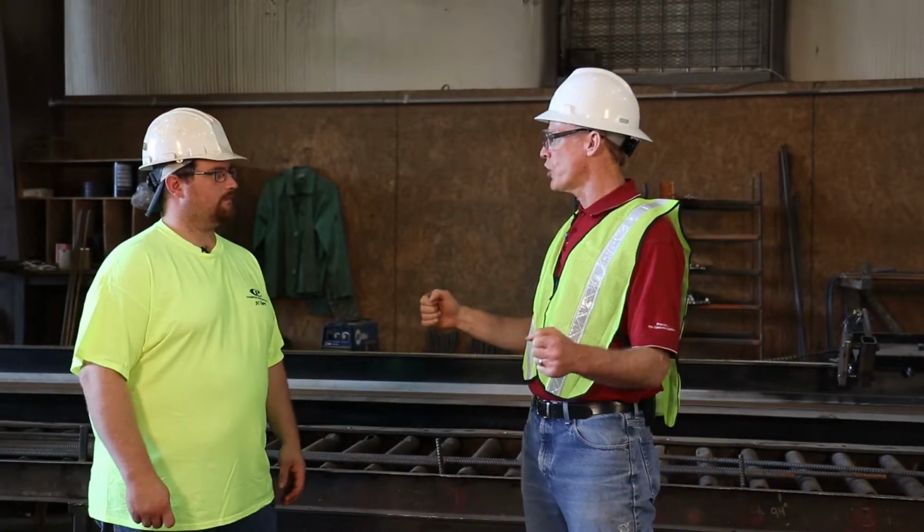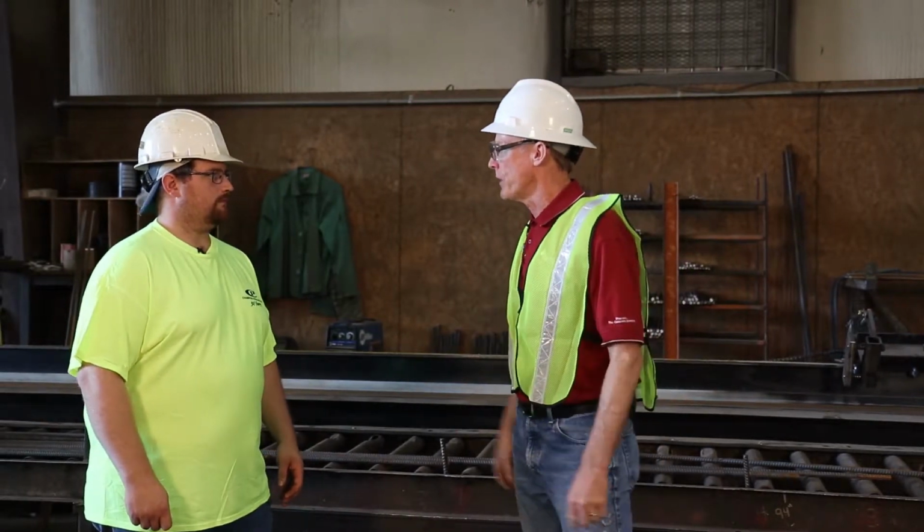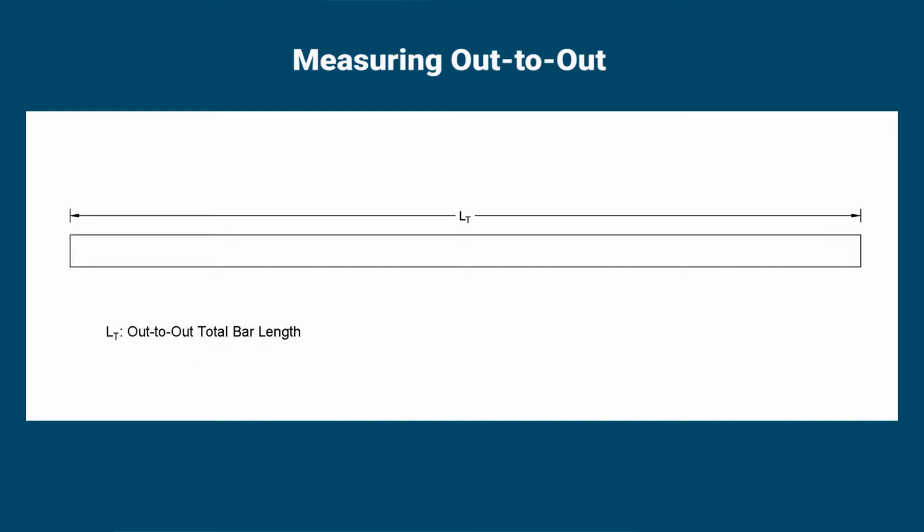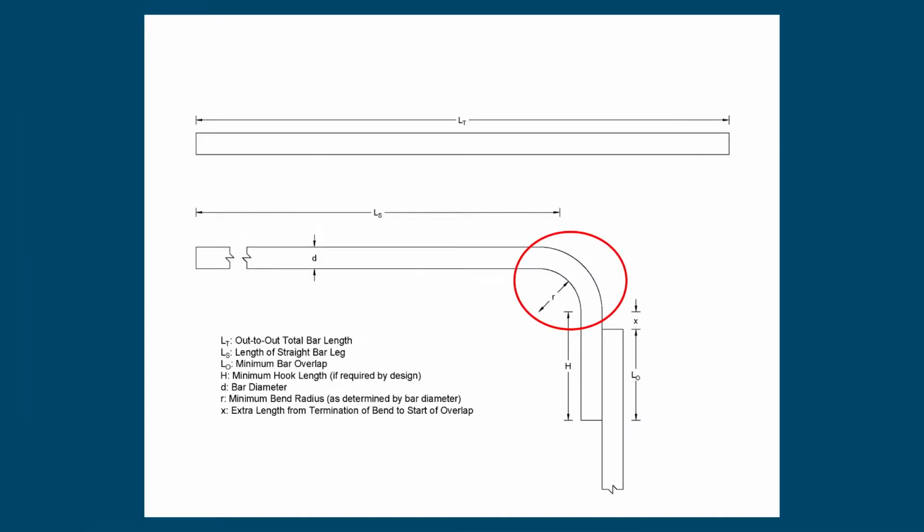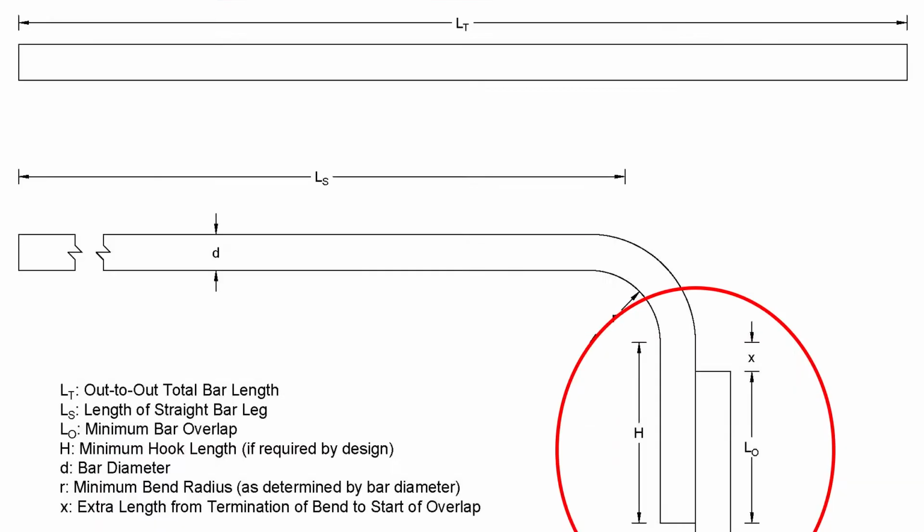You mentioned bending bar. Michael, how do you determine the length of your bent bar that you're going to make? So the key is to measure from the outside to the outside of the final bent bar. So be sure to include necessary length, including the correctly curved section, so that when setting the form it will meet the minimum concrete cover requirements and be within the required tolerances.